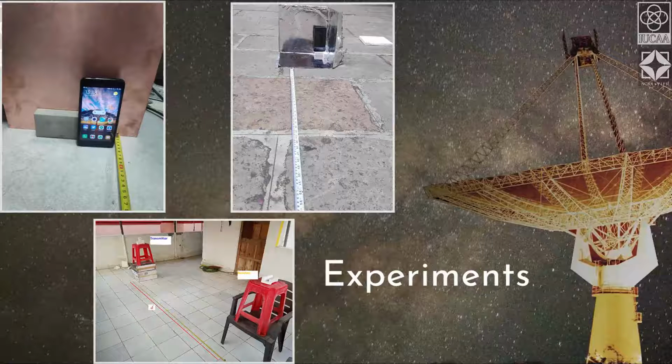Keep your transmitter at a center point and move slowly a little bit away, maybe 0.1 meter or 0.25 meter. Step by step you can go, and record the power in dB.